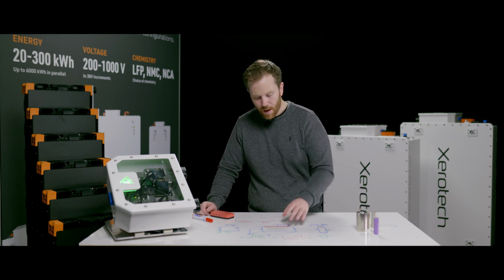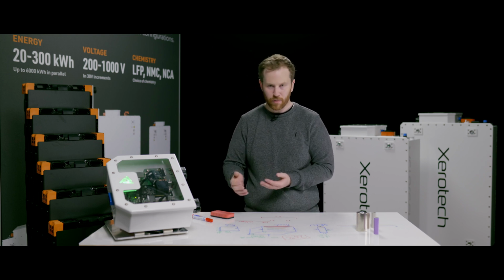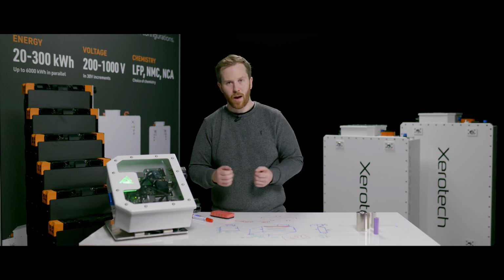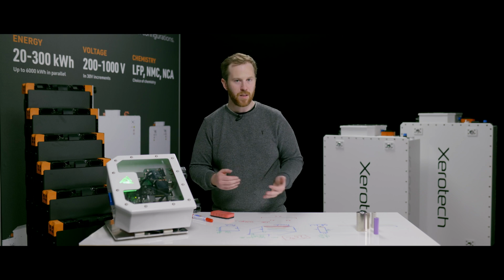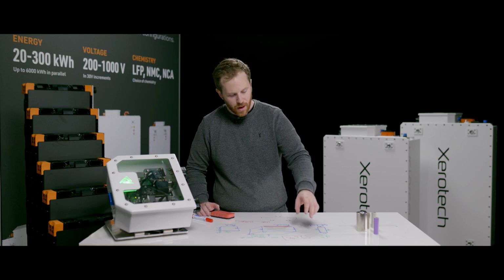But having said that, there are many applications in the world where large format prismatics, particularly LFP batteries that have lower thermal requirements, higher intrinsic safety in some conditions, they make a great solution for certain markets. Likewise, there's an application for pouches because the cell design enables much lower internal resistances of the cells because of the tab design. This means that a lot of the highest performance power packs for hypercars and VTOL electric aircraft applications are usually pouch cells for these reasons. So there's different applications for different cell types. There's no one cell is better than the other.